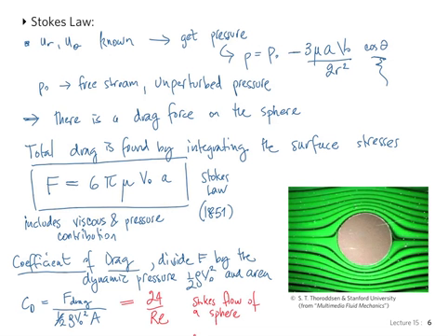We can do it numerically if there's a general shape, but it requires you to know the stresses and the pressures, because there's a contribution from both tangential and normal stresses, and sometimes you don't know that. So then you would have to do some sort of numerical calculation to obtain the pressure. That's why you can get it from computational fluid dynamics. But for general cases, you can't really get a closed form solution, a neat little result like that.